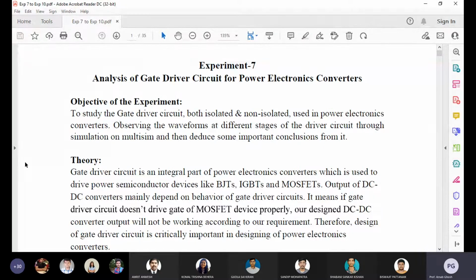The MOSFET circuit may be 600 watts, or maybe 100 watts, and your gate driver current rating is minimal, in the milliampere range, at 15 volts. Multiplying 15 volts by a milliampere gives you the power rating of the control circuit, but the power circuit rating is much more. So the control circuit will automatically be damaged and burned out.